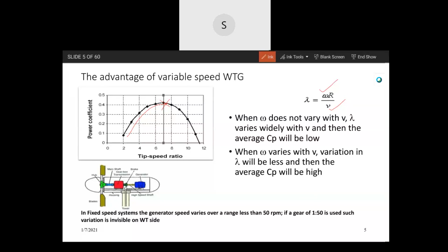You know that a 4-pole machine, whether induction or synchronous, when it operates at 50 hertz, the speed has to be around 1500. If it is a synchronous machine, it operates at 1500. If it is an induction machine, it will be around 1500: in motoring mode it will be below 1500, otherwise above that. If you want to change that speed, you have to change either the frequency, but for grid connected systems changing frequency is not possible unless we make a synchronous link, or otherwise we have to change the number of poles.